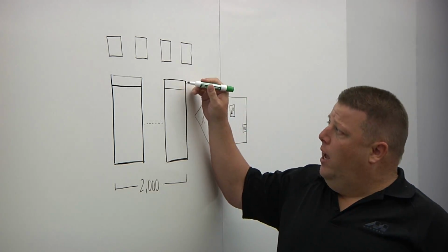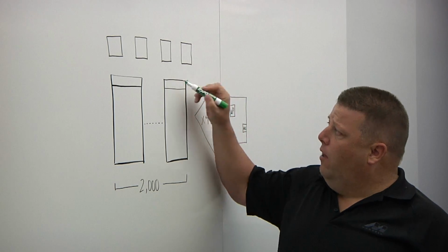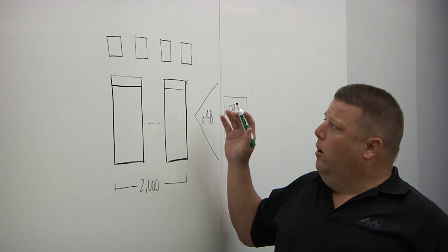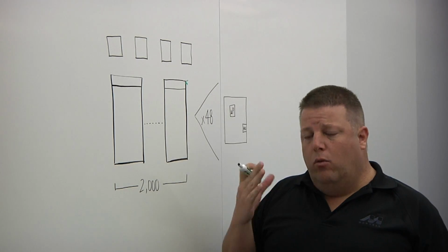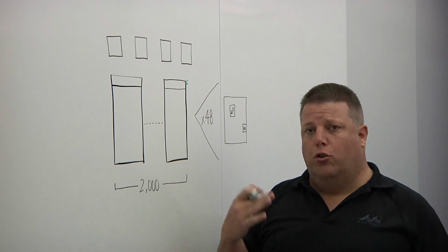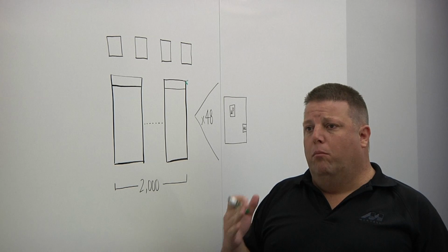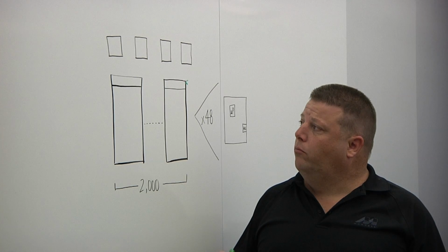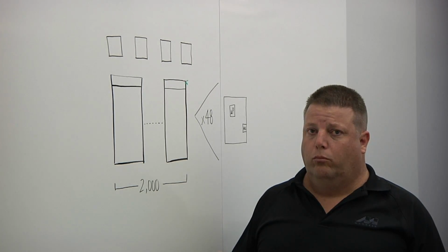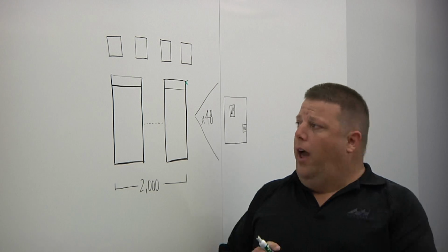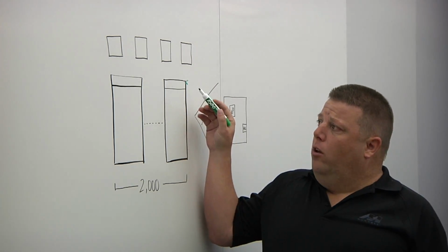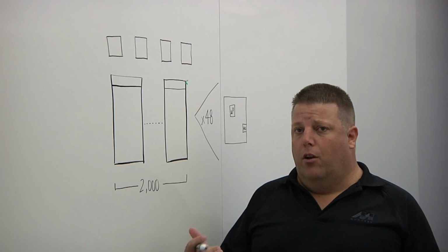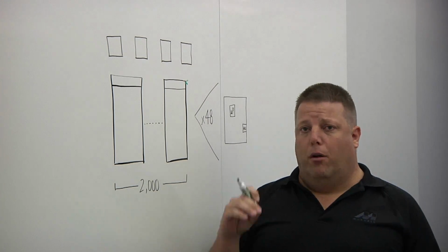So the challenge today is the development of the ASICs that go into the top of rack are a long design process, and at the time you design them, you have a limited scope of port speeds that you have to choose to support. And so you end up usually with a superset of what is required. So in 2012, we saw the introduction of the 802.1BR standard. What did that do? 802.1BR fundamentally changes the controlling bridge processing element of the network. It allows you to implement port extenders with a control bridge as a separate processing unit.